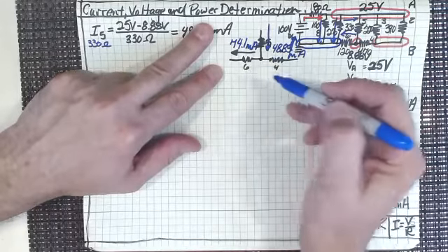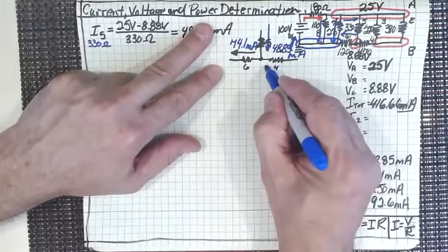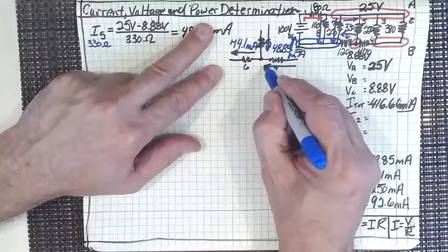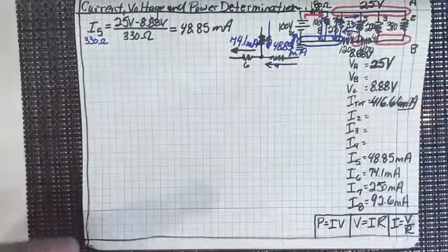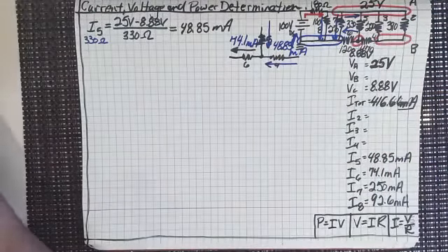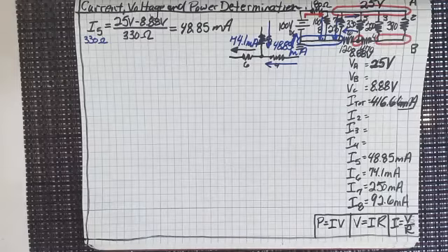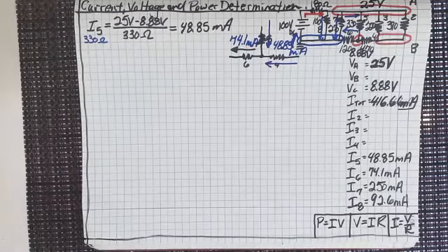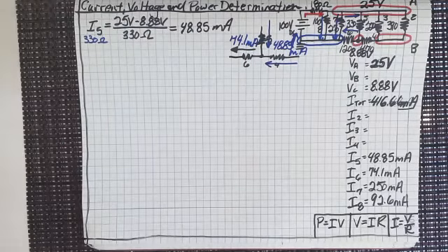So if that's coming in and that's going out, what that means is that this has to be coming in too, doesn't it? And what is the current, using Kirchhoff's current law? I'm getting ahead of myself. What is the current that's going to be flowing into that node? We know that the summation of currents into the node has to equal 0. So we've got 74.1 milliamps flowing out, 48.85 milliamps flowing in through I5.